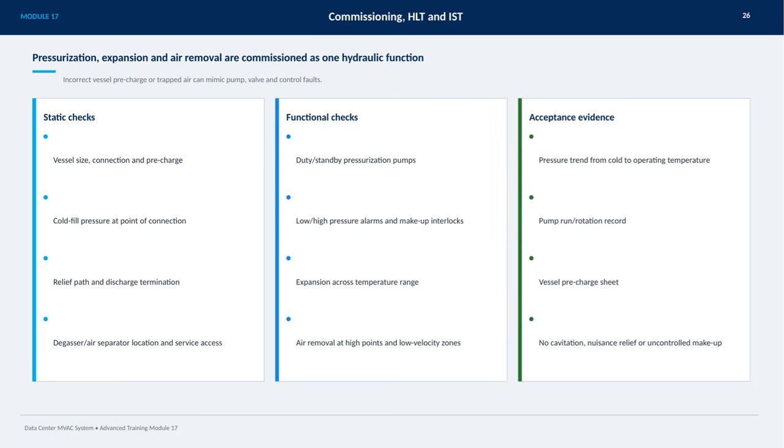Moving on to functional checks, we test duty and standby pressurization pumps, monitor low and high pressure alarms, and confirm makeup interlocks are operational. We assess expansion across the full temperature range and verify air removal at high points and low velocity zones to prevent issues.